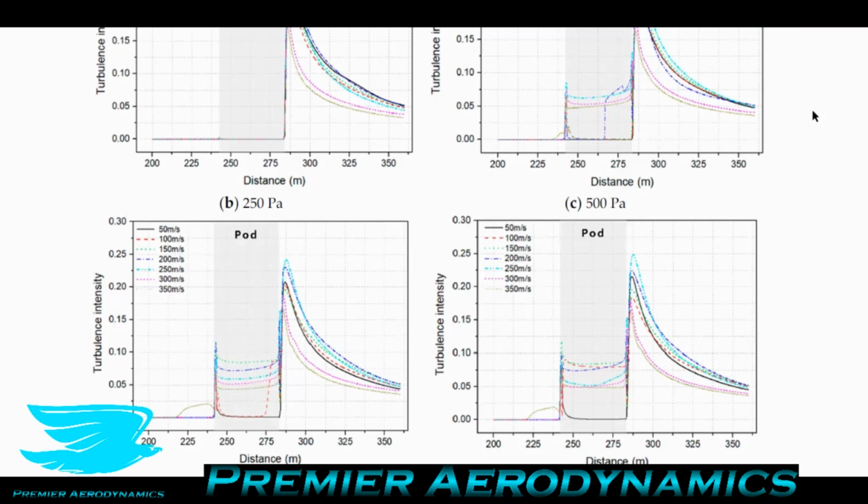And if you actually know what the angle of the shock wave to the wall is, and assuming the isotropic properties, which means that the flow stays about as chaotic as it was beforehand throughout the entire ordeal, you can calculate the angle which the shockwave will bounce off of. And I've done a CFD simulation on that on our YouTube channel. I think more than one, actually.